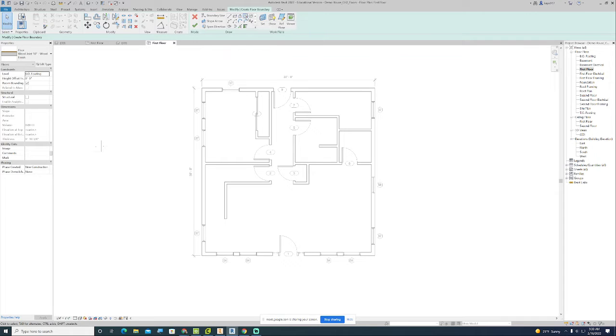You could draw an inscribed polygon, a circumscribed polygon, a circle. You could do arcs. Put a little round on the corner of the arcs. You could draw this thing called a spline, which is like a curve referenced by a bunch of different points. More commonly though, you have this other tool that says pick line. So if there's a line that exists, you can just select it.